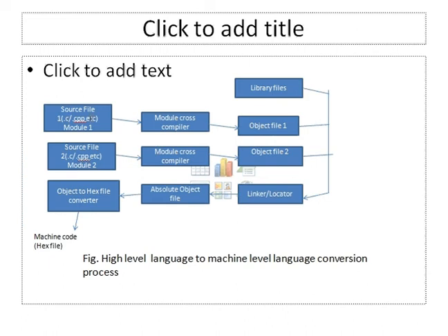For example, assume you are including a library for writing Part B experiments. You have used the LPC17xx.h header file. That header file has the core instruction set of your Cortex M3 machine. So all of these are actually library files, and they are resolved when you link, because we are supposed to use this device header file that has a huge number of definitions addressing your Cortex M3 machine.